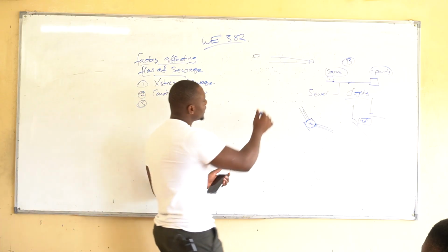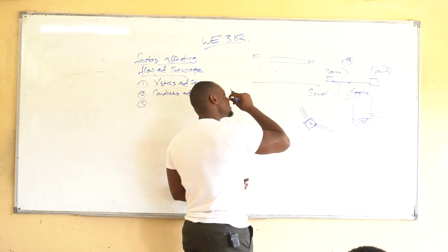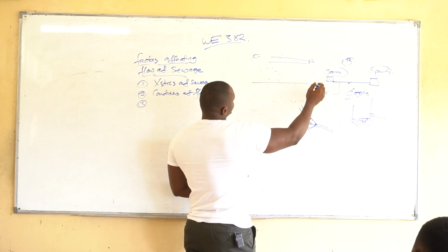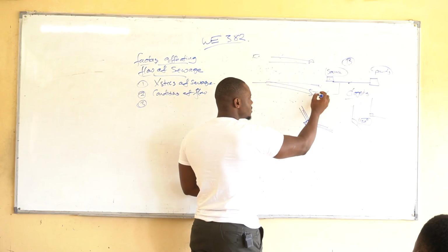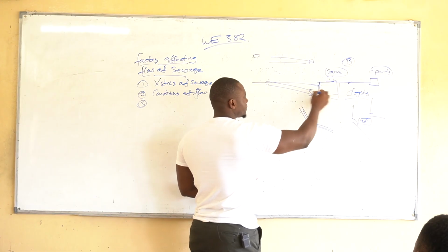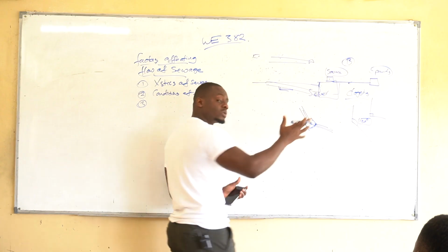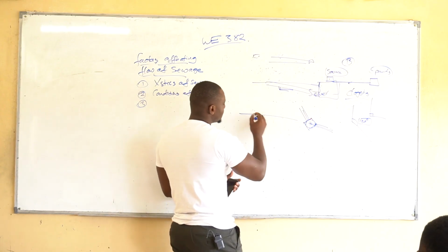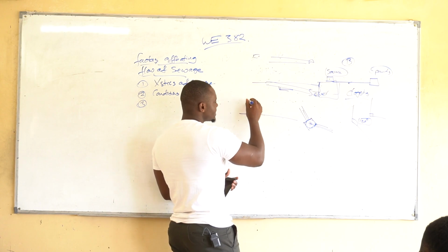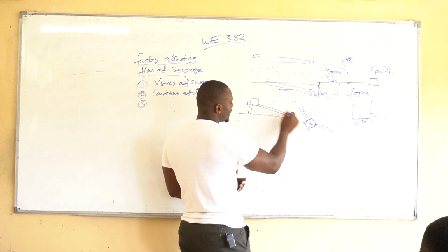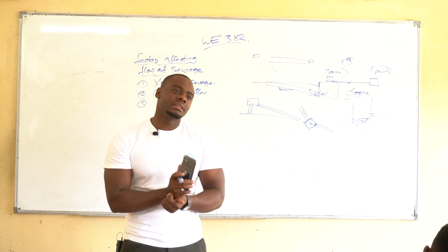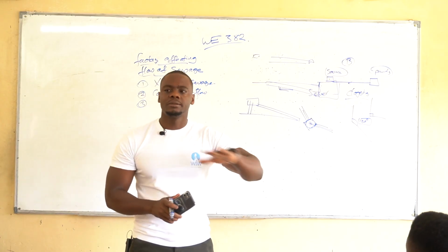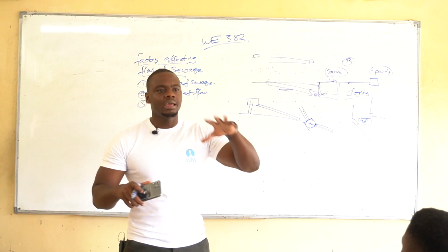It could be that this is your ground level surface. You can either begin to dig so that you give that slope and it has that gradient of some sort, or find ways of elevating your effluent and then let it just flow by gradient. But ideally, you're supposed to survey the place, know which are your high points and your low points, and then you decide.